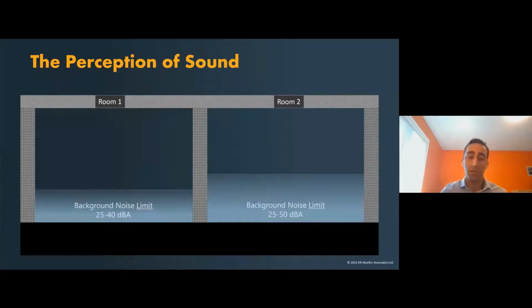We also need to establish expectations for noise resulting from occupant activities such as speech, which is not captured by the previous noise limits. We're going to assume a level of 75 dBA, which is consistent with the sound level for normal vocal effort, and that's for speech. And it would be a general or conservative estimation for typical noise in an office.